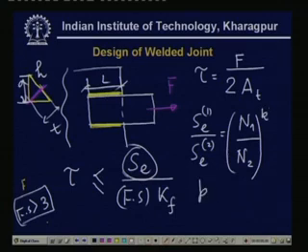So, now this factor K is about 0.13 for butt joint and from 0.15 to 0.18 for the fillet joint. So, this is how we calculate this AC, that is the allowable fatigue stress. Theoretically speaking, we should not call it AC, but this is allowable fatigue stress for different number of cycles N1 and N2. So, this is how this design is done.